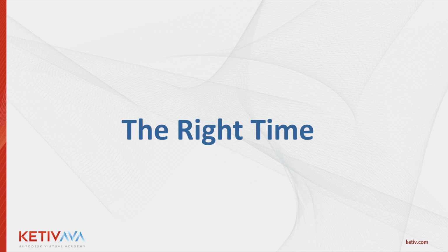So if you're using Inventor 2017 and you're trying to access data on a Vault 2016 server, that doesn't work. You're going to be disappointed, right? No problem going the other way around. If you upgrade your Vault first to 2017, it will allow one release back to access the Vault.